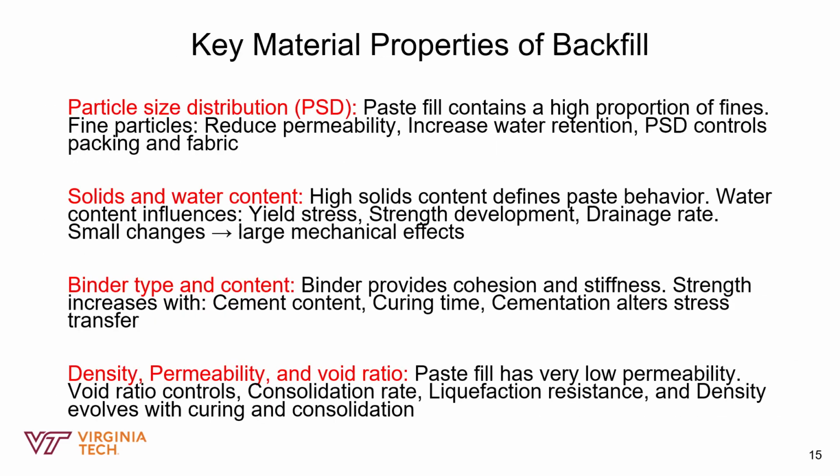Let's look at some key properties of backfill. The first is the particle size distribution. As I mentioned in the previous slides, paste fill is defined by the proportion of fines, and these particles are what reduce the permeability and trap the water. They basically control how packed the backfill gets and how tightly the grains fit together.